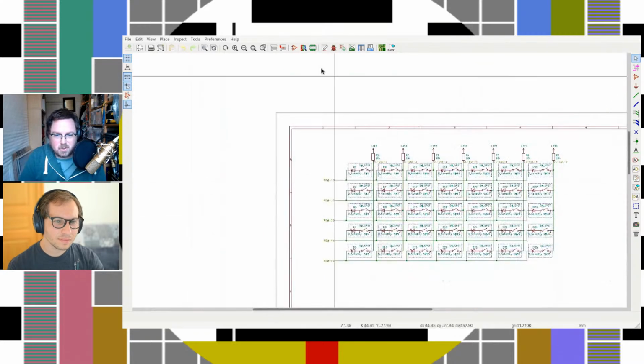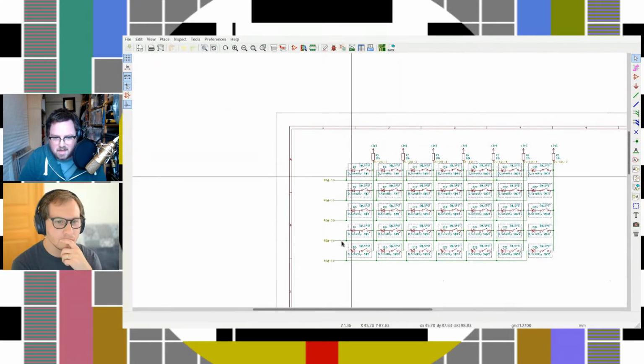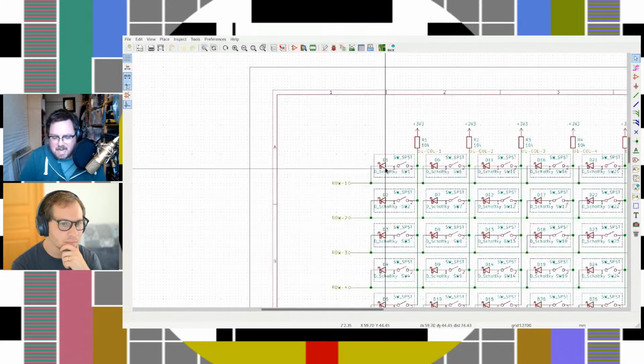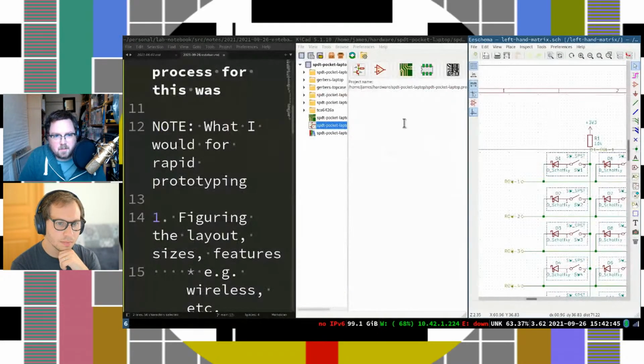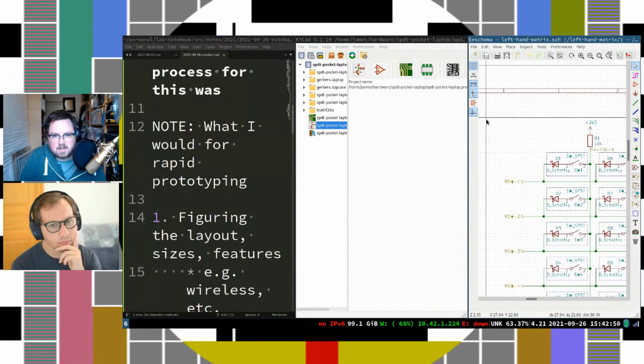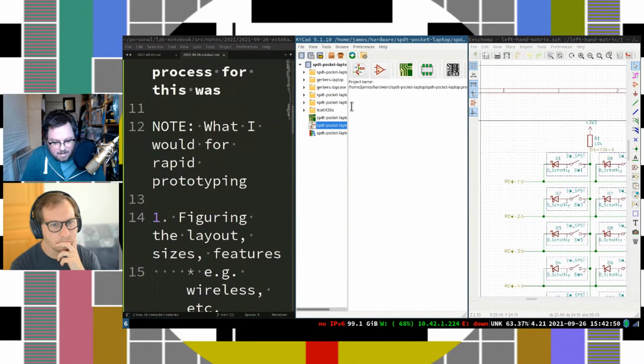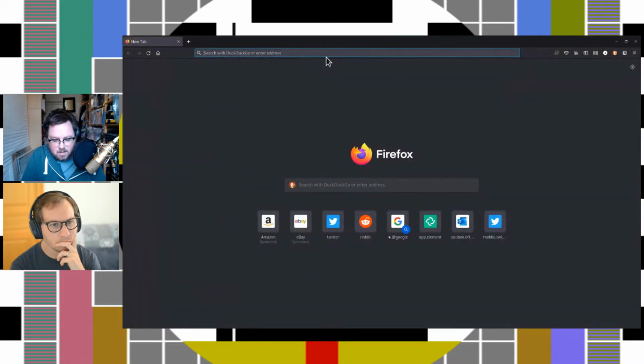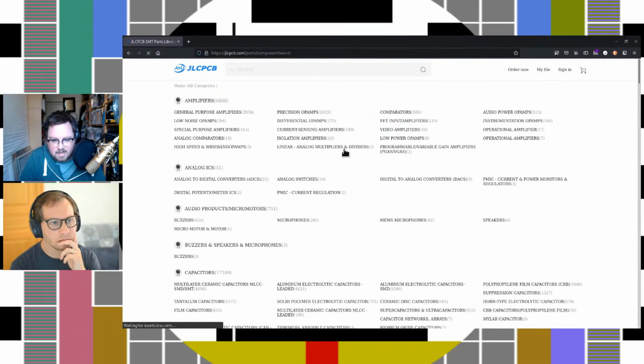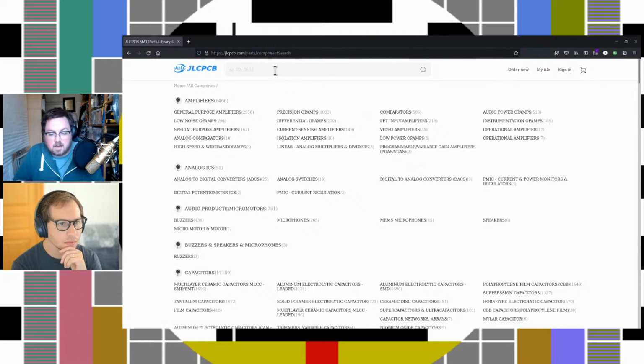So I think I just Googled keyboard matrix layout, saw this, and knew I had to have a diode that was fast enough to make sure I didn't have to wait too long before reading the pin. And then from there I figured out what diodes I should get. I know that JLC PCB has a search box that lets you see what kind of diodes you can get. You could do the same thing on DigiKey or Mouser if you were ordering the parts, but you'd pretty much go somewhere that would have the components.